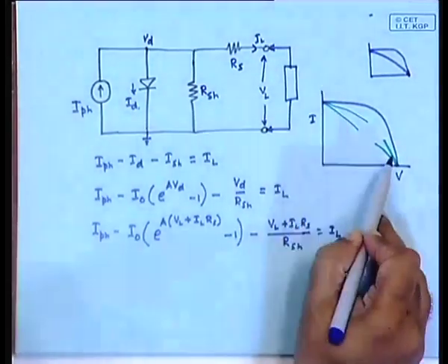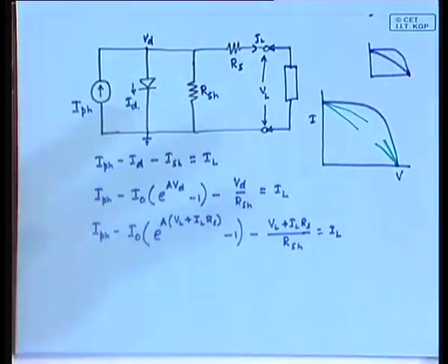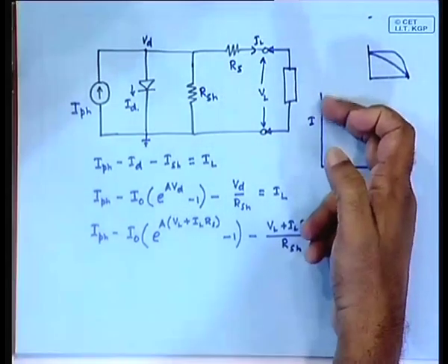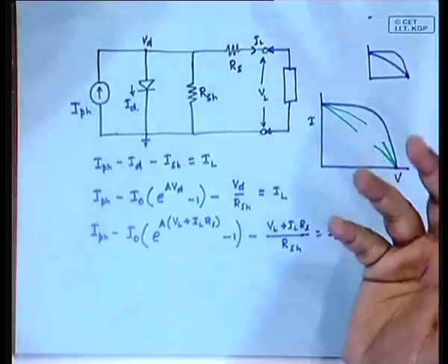So, the effect of these two would be like this, and as a panel ages, depending on which side is deteriorating faster, you can easily understand what kind of effect it is having. So, it is also possible to figure out which part is deteriorating faster, but often it is not possible to take corrective action because this is a solid thing, you cannot really change it. So, you only have to understand when you really need to replace it, but normally a photovoltaic panel runs fine for 20 years. Okay. So, this part is understood, I guess.